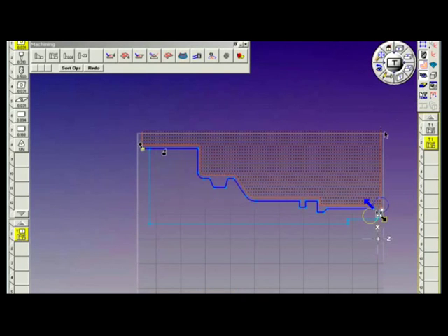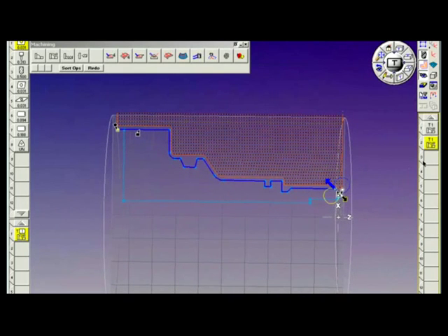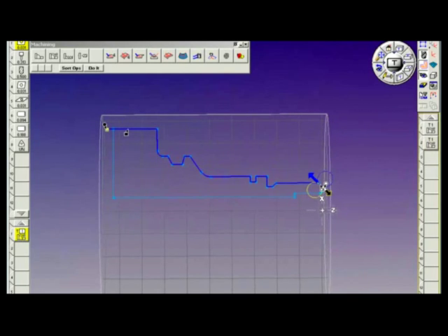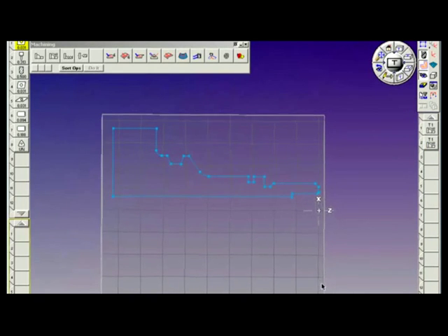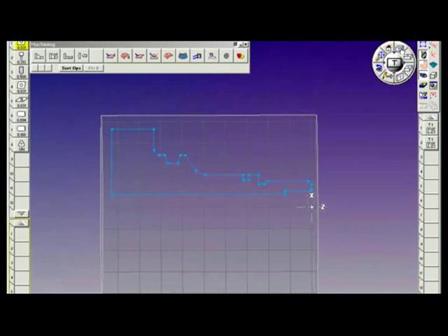Okay, turn off rendering, and I'm happy with this operation, so I'll deselect the operation to lock in the toolpath, click off the part, which eliminates the markers, and at this point, I'll throw away the process. I'm going to start a new operation with a clean slate. And this is always recommended. When you're going to start a new operation that doesn't use the same tool or the same process, always deselect your operation, deselect the part geometry, and throw away the process. This ensures that you don't overwrite any previously created operations.